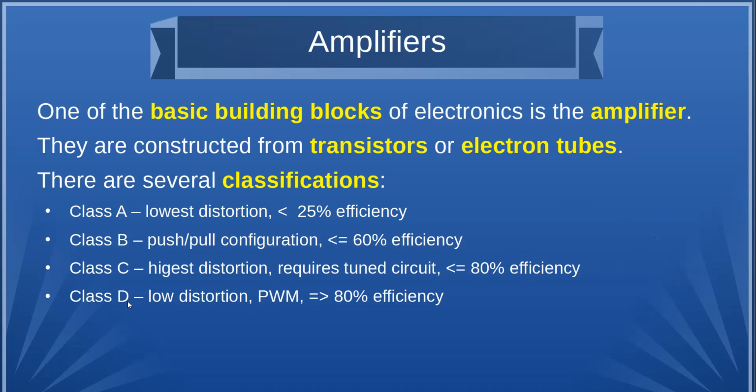And then there's class D, which some people call digital class. It's not really digital, but it does use sort of a digital technique in that you feed the analog signal into a pulse width modulator. So you get square waves of varying width out of it, depending on the input voltage. And those are easy to amplify digitally, and then you run it through filters to get the audio frequency back. They typically only use these in lower frequency audio work.